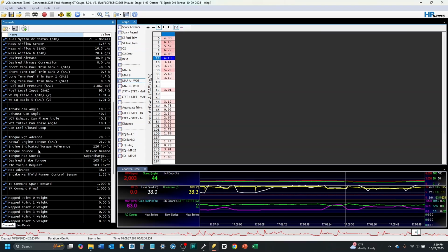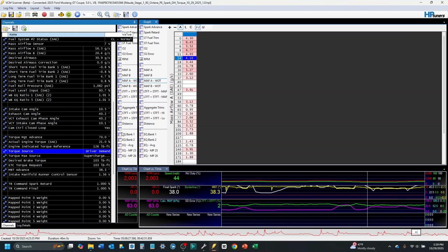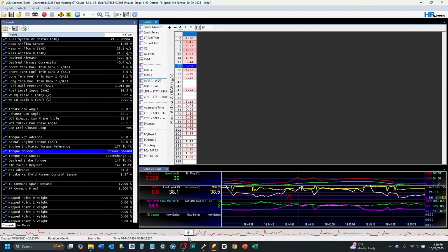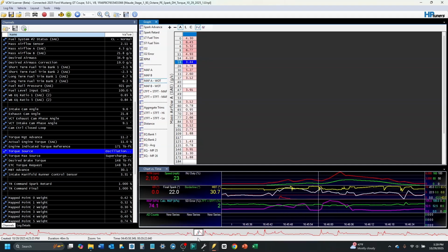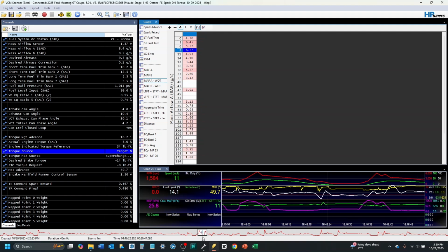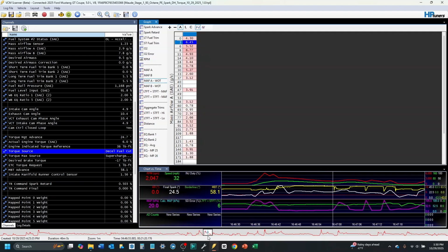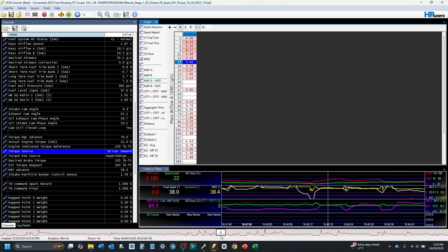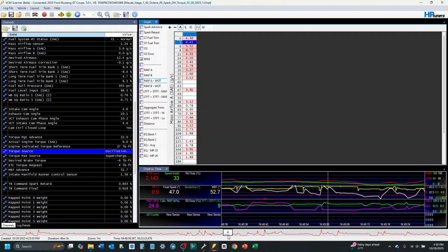And so then, torque. Torque source and torque max source. Okay. So for these, again, looking at some of our power stuff, idle speed, oscillation, decel fuel cut. So there I was decelerating, so that's where I was getting it from. That's all good. Idle speed. Torque max source is still the, what's the supercharger load limit? That's pretty cool.